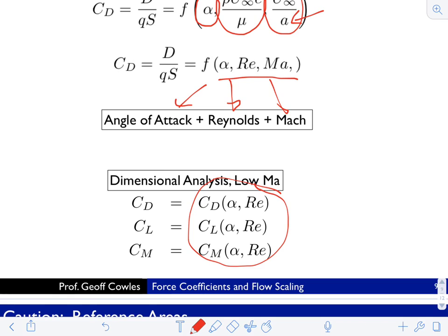And so when we get into foils, we'll study a bit more: when is Reynolds number really important and when is it not? And that is a really important question to get at. And there are some differences in whether you're talking about lift or drag. When it comes to drag, Reynolds number is essentially always important when you're thinking about skin friction. It's directly dependent on that Reynolds number.